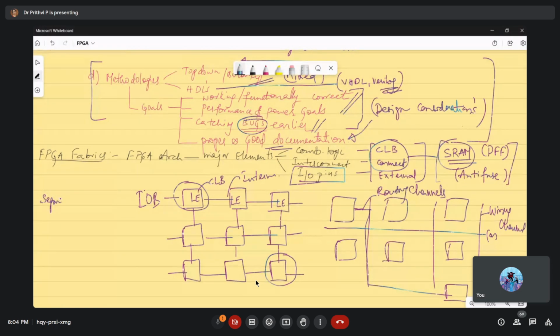That means segmented wiring is there. So I have four logical blocks, say 1, 2, 3, 4. If I go for shorter wiring, where each wire is of this short length, and I want to connect logic element 1 to logic element 4, I need almost 3 delays here, because each node or point of connection is to be programmed. It is not as simple as showing a dot here. This has to be programmed. That means 4 programs almost have to be given to reach this segment.